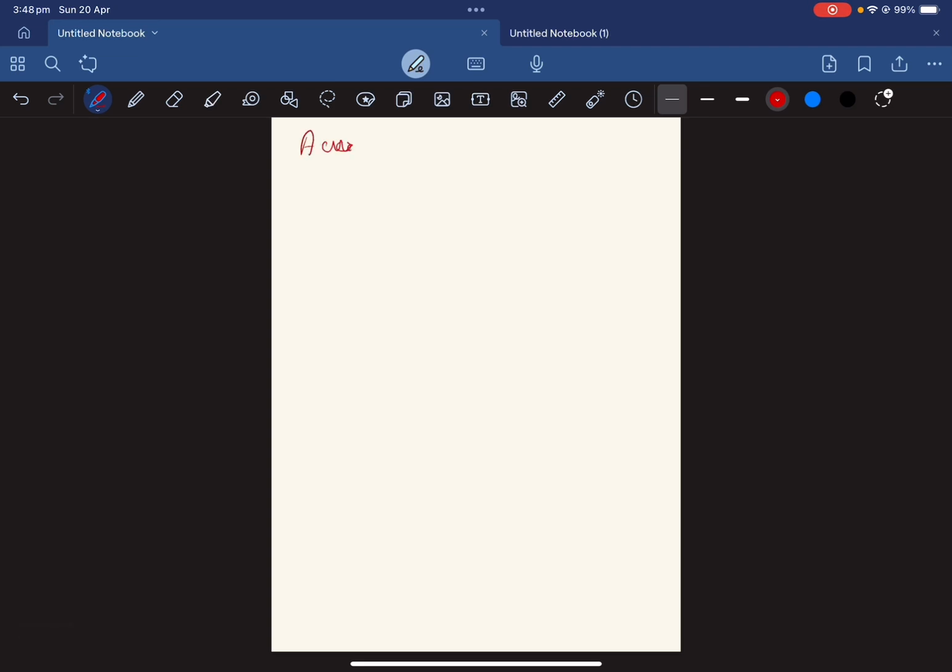which is aerodynamic balance. Let's discuss what aerodynamic balance exactly is. When you move your control surfaces, say the elevator, the airflow will try to resist that movement. So it's not going to be so free that you can move it with one finger. There's going to be some resistance from the airflow.